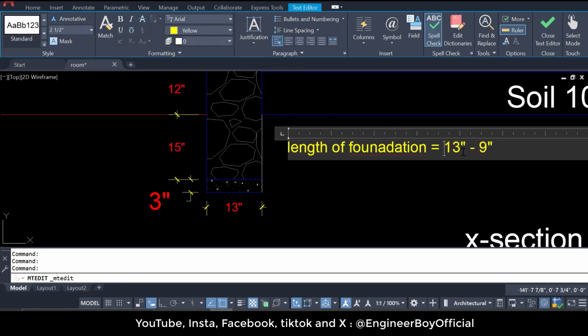So basically what I'm going to say is the length of the foundation is going to be the length of the wall, which is 13.5 feet, if you remember. And we will have a summation of this ratio. We will subtract the wall thickness from the thickness of the foundation. The width of the foundation is 13 inches, and we will subtract 9 inches because that is the width of the wall.